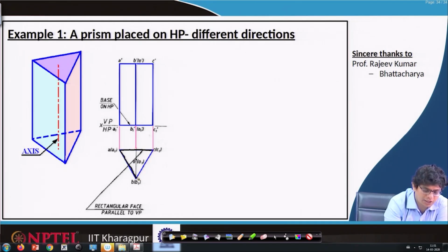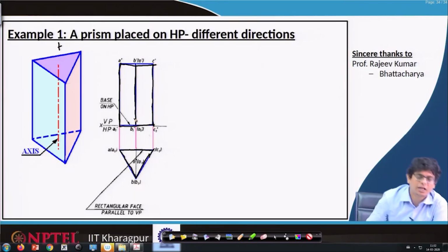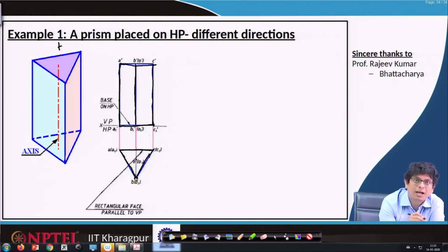Anyway, the projection on the horizontal plane, if we are looking, the top view will always be a triangle, and when we are projecting onto that vertical plane, because one of the faces we will be in a position to see, that is this rectangle. The edge we will always be seeing, so that will be this one, because this edge, whatever the line passes through that, we will see it as a line there.